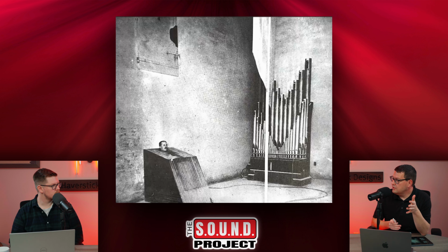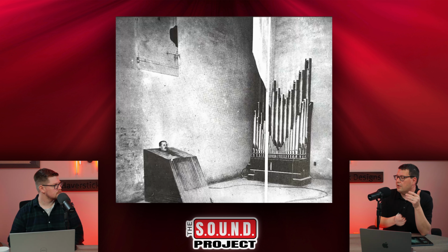This is where a lot of the acoustical treatment manufacturers test their materials, where you actually measure the room when it's completely empty and get the reverb time at various frequencies. And then you place 72 square feet of an absorption material inside the room, and you measure it again. And from the difference between the reverb times, there's a calculation to figure out what we call absorption coefficients. And absorption coefficients are a metric that we use to see how good materials are at absorbing different frequencies.